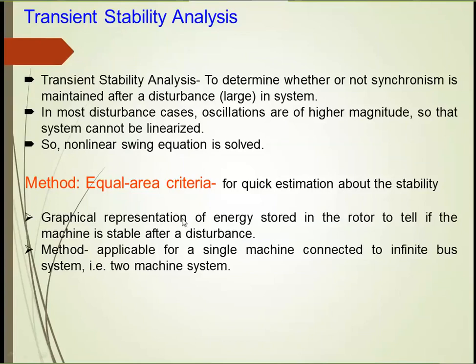So in fact, this method is a graphical representation of energy storage in the rotor to tell you whether the machine is stable or not following the disturbance. But there is a limitation here. The machine has to be analyzed as a single machine connected to a large network.